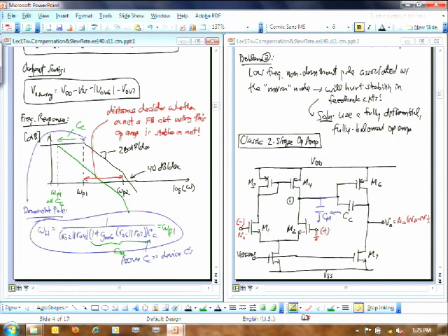Okay? Yes, that's right. It seems like it would be decreasing your bandwidth. You are. I thought with negative feedback, generally it increases bandwidth. You do. So in the end, this is the open loop op amp response right now. So we actually have not applied feedback to this yet. We're just changing the open loop response. And then when we do apply feedback, I'll be able to draw a line across here, and then it'll follow the green line. You see that? But everything I'm talking about here is open loop.